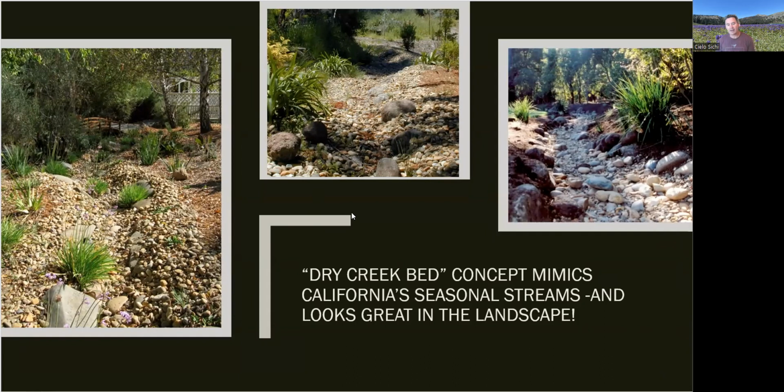Now, rock gradation or sizes of the gravel, if you can switch up the sizes, you get a much more natural looking system. So you can see here, there's some larger cobbles, some bigger boulders on the shoulder here, and then some more finely graded gravels that go in between. And if you go out to the river or the creeks and you look at them in the drier season, you're going to see what this really looks like. And the goal is to try to replicate it.